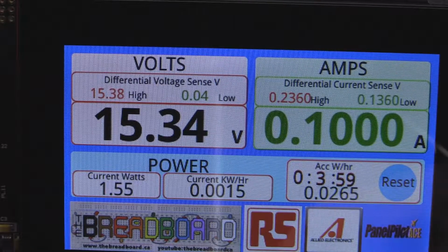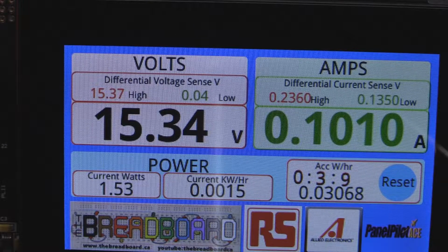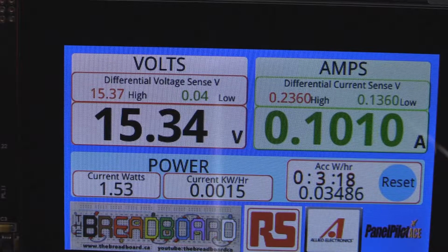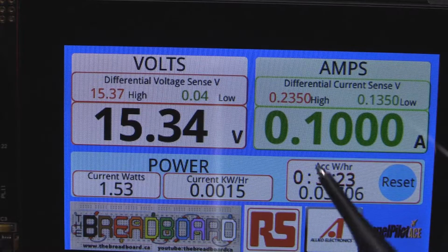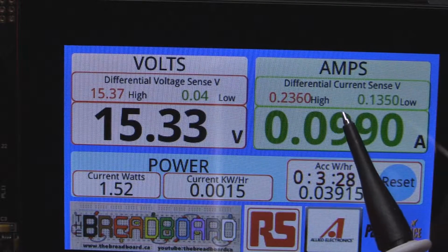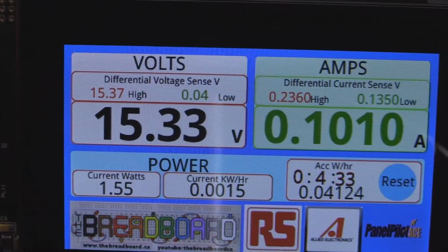And my voltages now, if I just bring this one back up, excuse the noise. All right, I have 15.32 volts directly across the LED, and I've got 15.376 volts up on the output of the power supply. So you can see that there's also some extra voltage being dropped around the place. Now obviously 100 millivolts of that is in the current shunt resistor sensing. So anyway, let's just start cranking this up a little further.